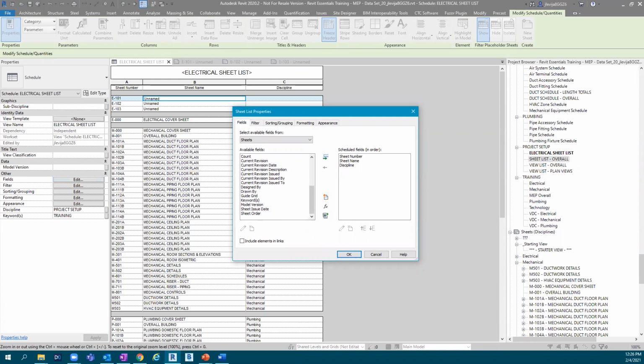So I've got a question here. So you've added it to the title block. It is a custom parameter in the title block family. So yeah, you'll see in some title block families, they're added in there already. Other Revit sessions, depending on kind of what you're working on for your project, will not necessarily put it in the title block family. It will be added more along the lines as a project parameter. So those are two options, and I believe this one comes from the actual title block family. So when I brought the title block in, it brought that parameter in with it.